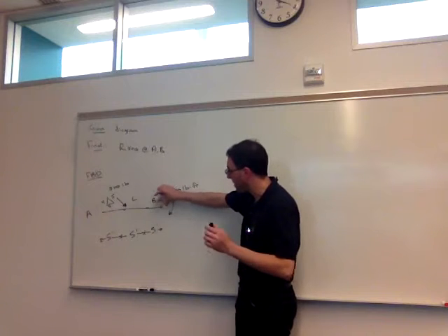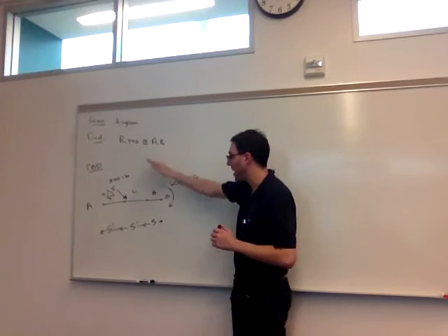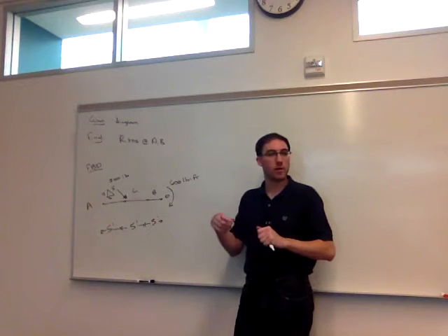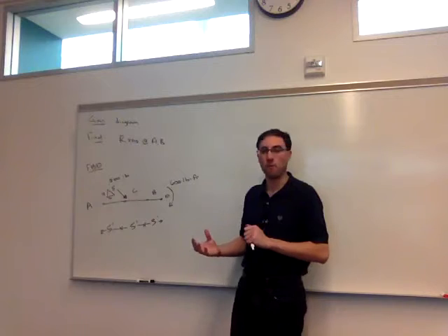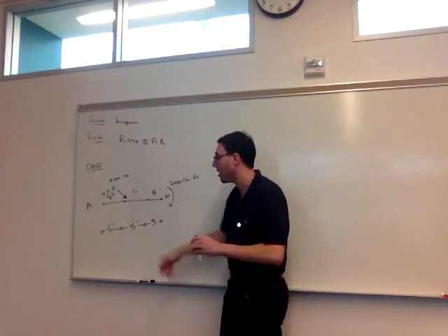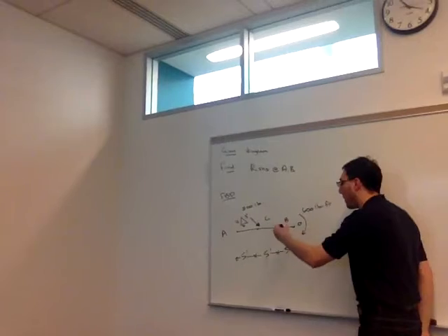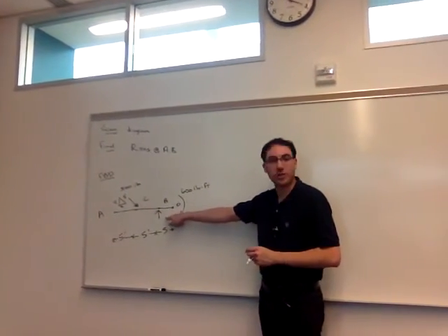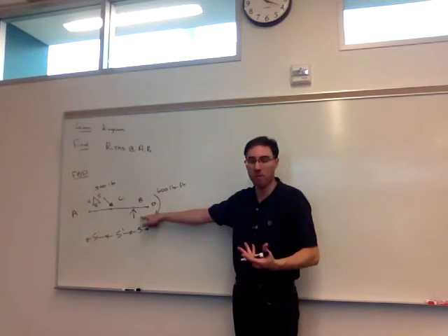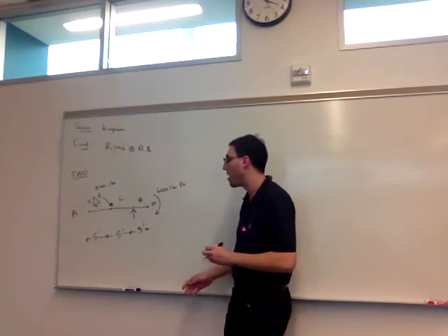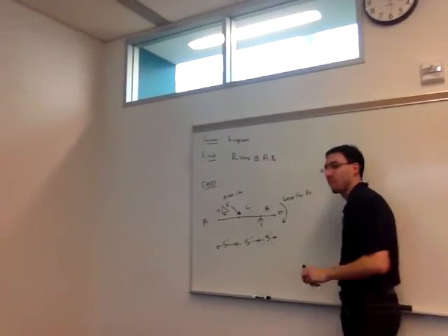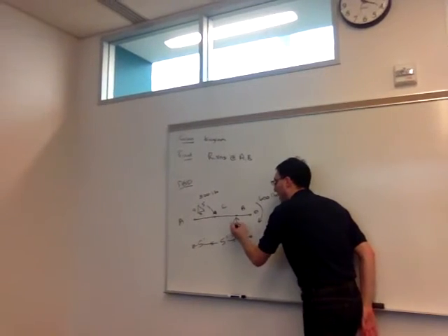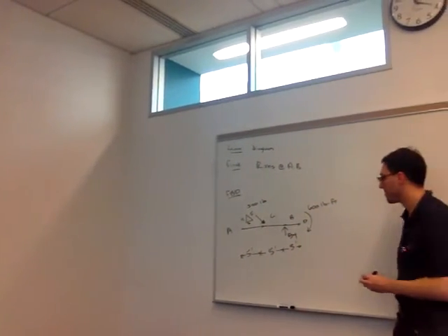Now because the ball is there, can we move our beam up and down? Right, we can move it up, because the roller, or that ball, really is just going to be a normal force. It prevents us from pushing it down, which means that the ball exerts a force up on our object. So we know the direction of this has to be up because it's basically a normal force. So we know it has to be up, along this vertical axis. So I know its direction, but I don't know its value. I'm going to call this By.